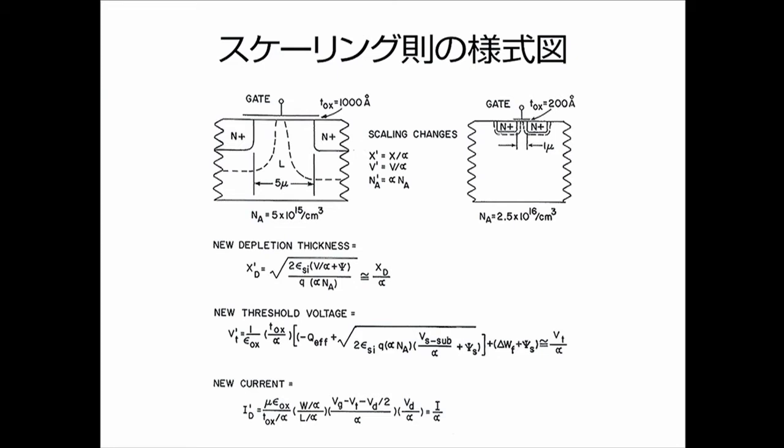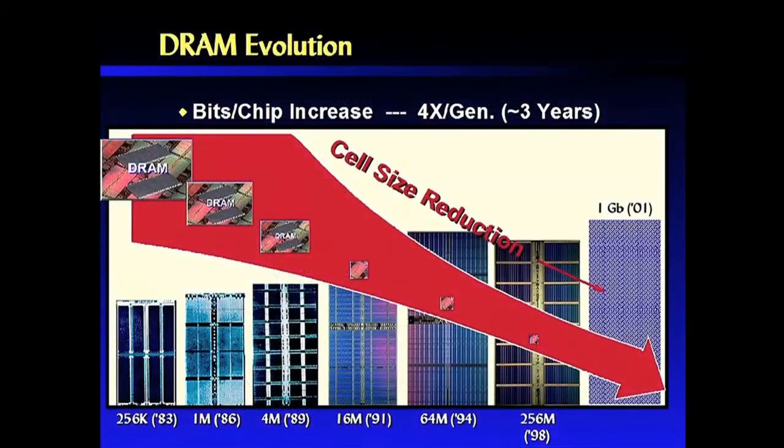In 1974, 7 years after his publication of the DRAM, Dr. Dennard and his colleagues at the Research Center published the scaling theory, the design guidelines for transistor miniaturization. The theory says that the operation of the transistor is guaranteed when the length, width, and height of the transistor are reduced by the same proportions, and when the voltage is also altered by the same proportion. This has contributed greatly towards higher integration, higher speed, and lower power consumption of the memory IC.